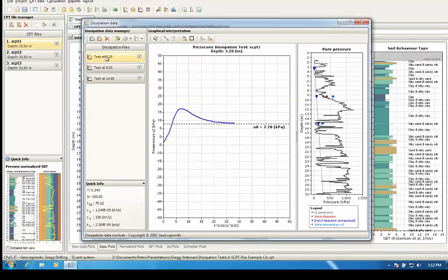Now, when you compare it with lab data, of course, remember often it's hard to get truly undisturbed samples, hard to get a lot of them, it's expensive. So samples are not always truly undisturbed, and then putting the samples into the lab, often it's quite difficult if you actually want to get the horizontal coefficient of consolidation, if that's the one you need, either for pile design or wick drain design, where the horizontal one is the one you want for design.